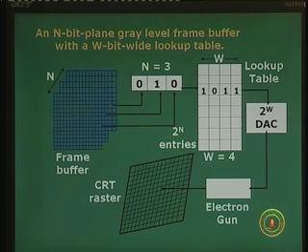whatever he needs to draw his picture or color, and then loads the corresponding 8 positions of the lookup table with only those intensities. So the programmer knows in what position in the lookup table his desired color is, any desired color, 8 desired colors out of 16. So he chooses 8 out of 16, loads the lookup table with the corresponding 8 entries and accesses it by a register. So that picture I hope is very clear to you,